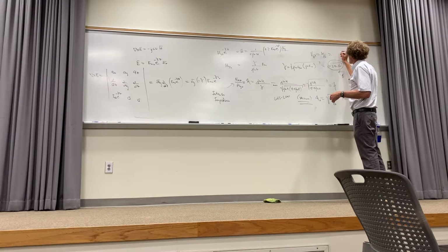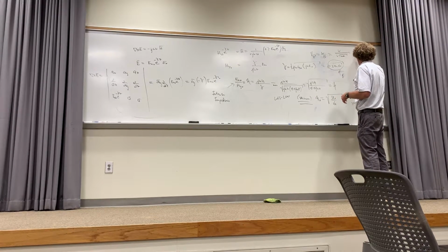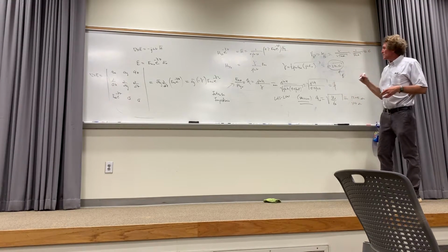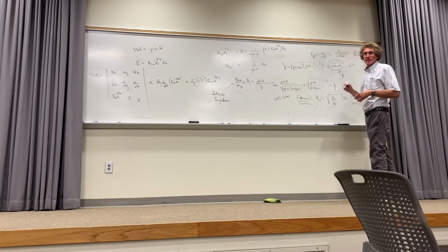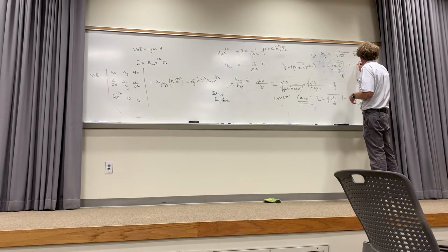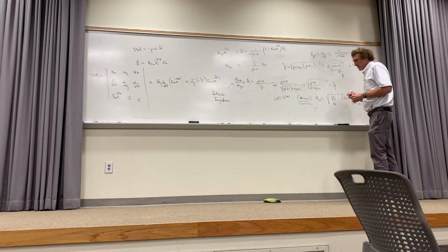Now, what is the velocity in free space? Omega over beta, which is omega over omega times the square root of mu naught epsilon naught, which is really 1 over the square root of mu naught epsilon naught, and that is c, the speed of light. Since we're on this topic, what is c approximately? Anyone? A value. How fast is fast? 3 times 10 to the 8th meters per second.